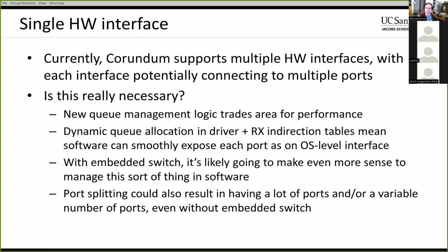I've also been starting to look at resurrecting some of the upgraded descriptor management and completion management code that I had a while ago. As part of that, it's going to use more logic resources, so if we just have one copy of that, that's probably going to be a good thing. I'll probably keep the option, if you do want multiple hardware interfaces, to configure that via module parameters. But by default, we'll flip all the designs to having a single hardware interface, and then the software will deal with presenting that as multiple interfaces at the operating system level.